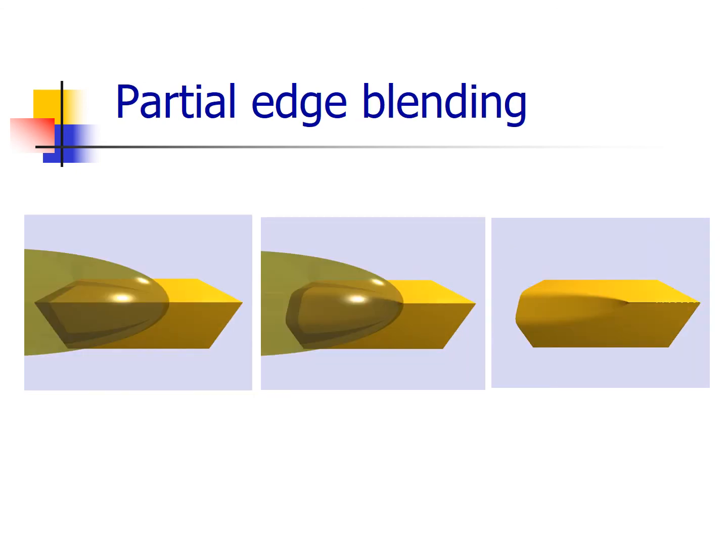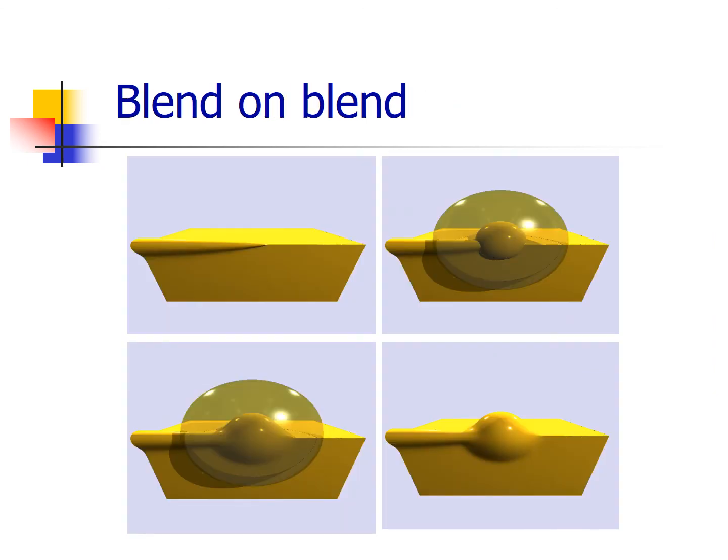Here, blending intersection of two planar half planes is bounded by an elliptical solid, which overlaps only with a part of the intersection. As a result, we can observe the transition of the subtracted material blend to the sharp edge at the point of intersection between the edge and the surface of the bounding ellipsoid. This is an example where we can use blend-on-blend operations.